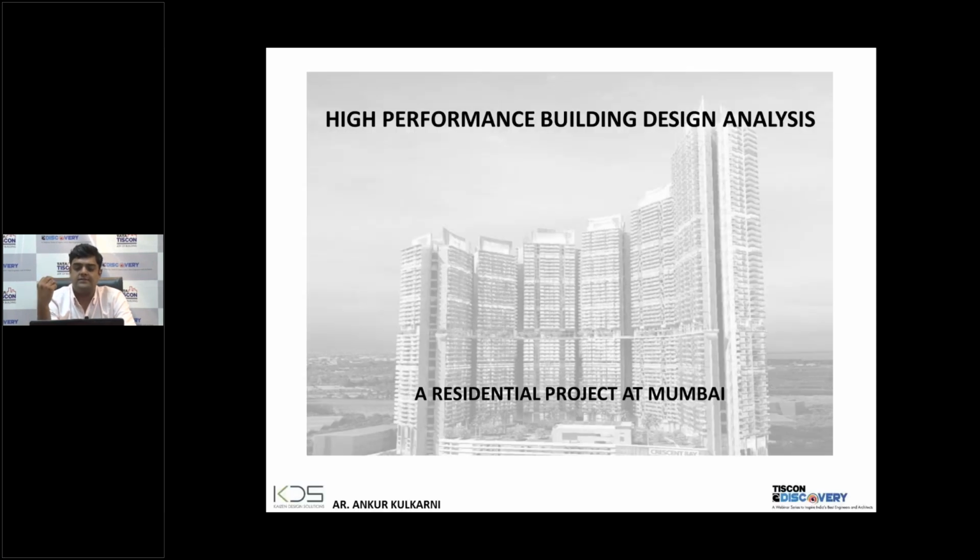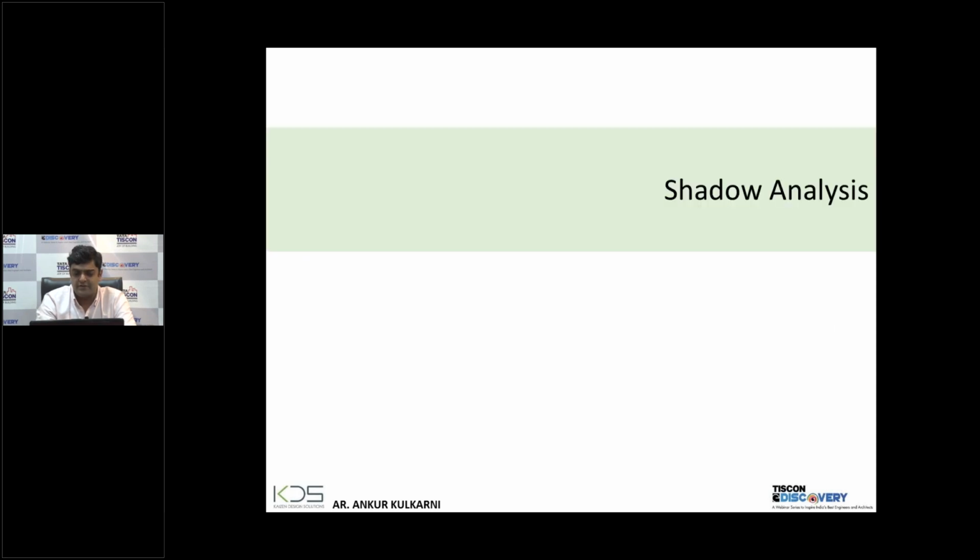I'll take you through a few case studies which we have done. To explain the concept in a simple manner, it is very important to measure the performance. When we say high performance building design, it mainly comprises, needless to say, energy performance, but also your shadow analysis, daylight, ventilation, heat island effect, wind analysis, everything is very important. So before you freeze on your design parameters, it is very important how you deal with your passive technologies and strategies. So this is a first step, shadow analysis, and this is a typical standard requirement